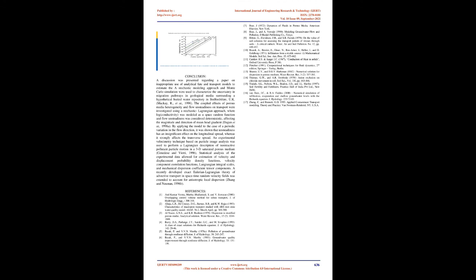A fully nonlinear analysis of the integral differential equation for the spatial second moments of the ensemble mean concentration in a heterogeneous aquifer was carried out by solving the nonlinear integral differential equation numerically and iteratively, Zhang and Qi, 1995. The effects of log hydraulic conductivity variance, Pe, and anisotropy then were investigated.